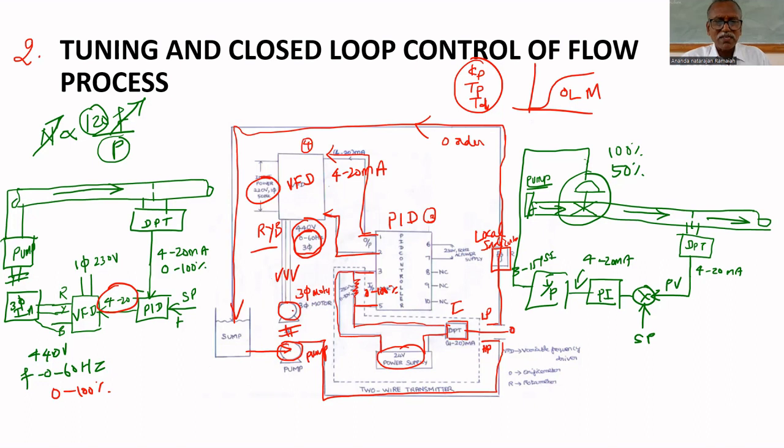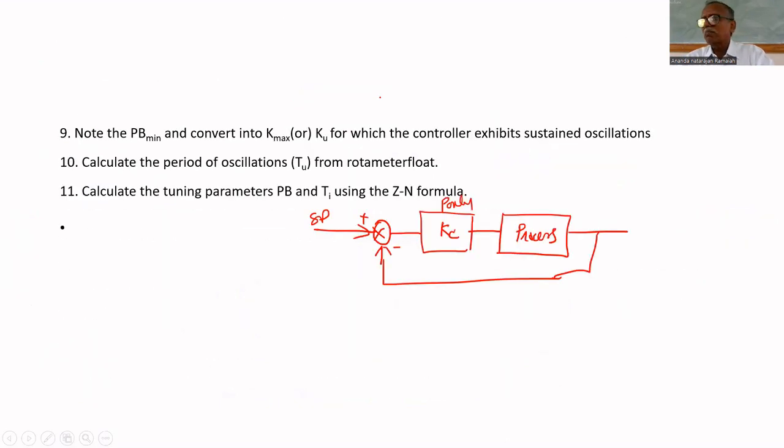Then the motor is there, fifth order. If you consider motor and pump together, it can be first order. So there are 5 components in series, at least fourth order, because theoretically the flow process is zero order. That's why the remaining 4, if you consider them, is fourth order. So if you increase Kc, it will definitely become unstable.